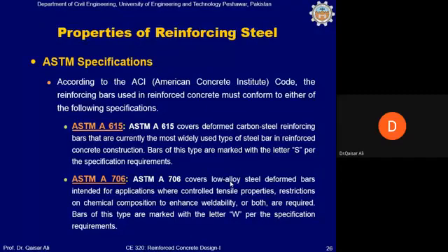You should remember this if you have ever studied the manufacturing of steel produced in a factory. The steel gets its strength because steel is an alloy made of iron, and you have heard the name blast furnace and other furnaces in which the steel is manufactured. During the manufacturing of steel, the strength of steel is achieved by adding carbon to it. So when carbon is added to iron during the manufacturing of steel, it will increase the strength, but it will decrease the ductility of steel.